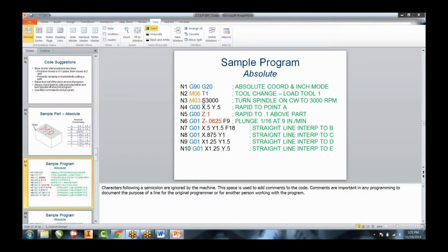Be careful about the spindle. If they don't actually simulate it in the software and they just do a verify, the verify can't tell you that the spindle never turned on. The verify will look nice, you get this little red cube, it's pretty, and they'll never turn the spindle on. If you use the simulation in CNC Motion, it'll actually come down to the material and tell you that an impact has occurred. So there's a big difference between actually knowing how to use the simulation component of CNC Motion rather than just that little red verify.